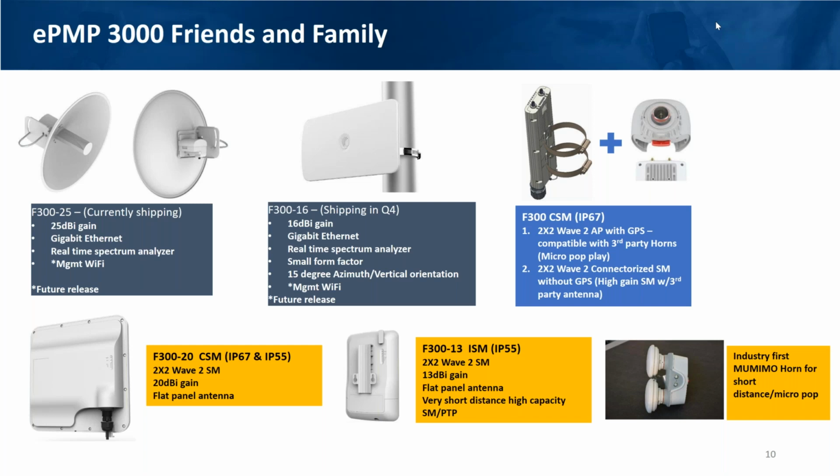You would deploy this just like you would deploy any other system that you do today. Leave it to the radio and the software logic to figure out how it's going to group and do the MU-MIMO part. The wider the distribution, the more chances we have of grouping subscribers. But because it's really just two subscribers you're grouping, a 10 to 30 degree difference between two subscribers, or 50 to 70, is all we need.